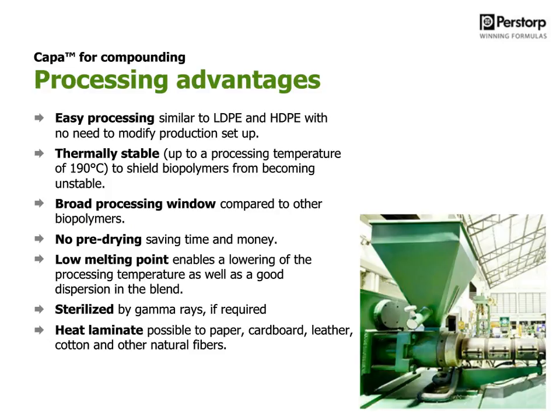Thanks to the low melting point and the stability of the product, it's very easy to process and introduce into your formulations. One thing you need to be aware of is that the low melting point can be a challenge sometimes, and you need to lower the temperature in the hopper to avoid that it clogs or gets sticky. But apart from that, it has a very nice dispersion and processability into the different formulations we have worked with. It has a very broad processing window.